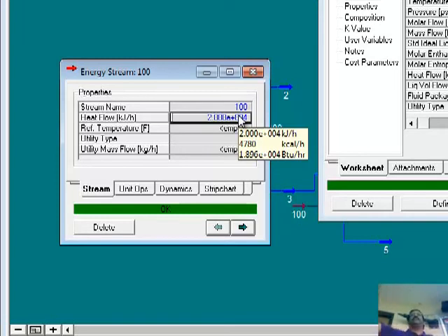You say, this is the output I want to adjust, and this is the input I can change. So I can couple the vapor fraction or the vapor flow rate to 25 and say, make the degree of freedom the heat duty. Then it will automatically solve it for you. I have not gone through this last night, so I don't want to try it live in front of you, how to use the adjust block.